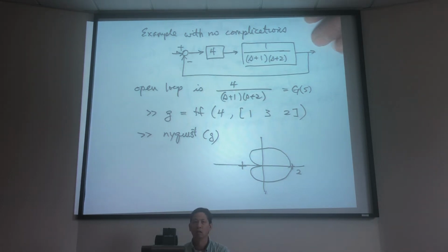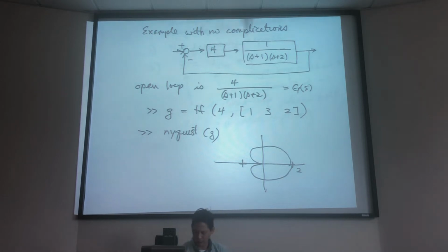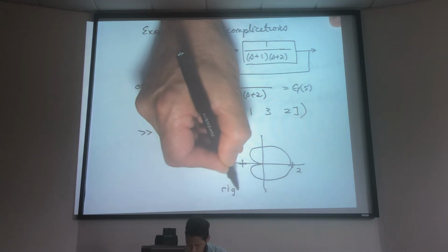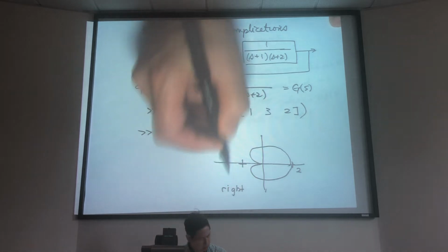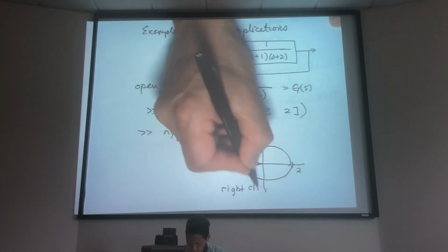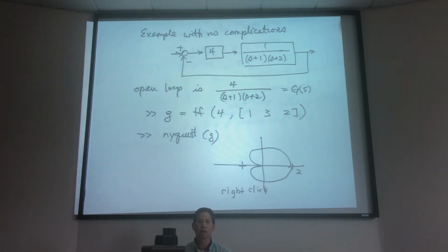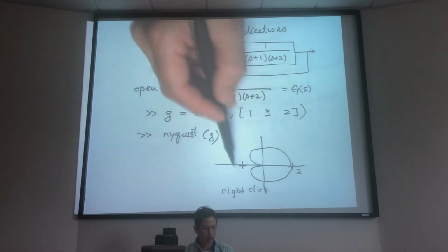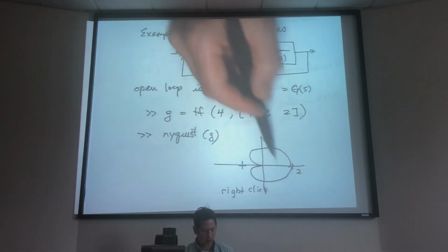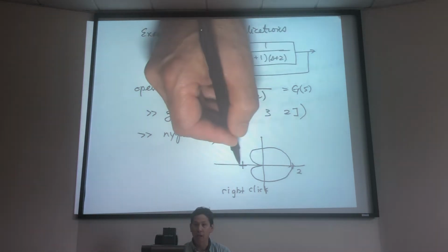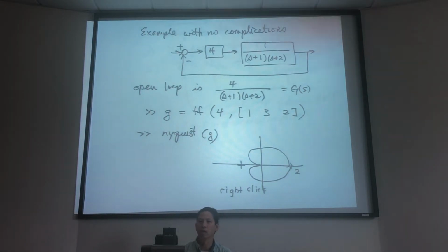Okay. Take a moment and right-click in the screen here. There's a sub-menu called Show, and turn off the negative frequencies so you can reinforce in your mind that part of the curve on the Nyquist plot is the positive frequencies and part of it is the negative frequencies. All right, and you see this. Is this kind of what you're seeing?